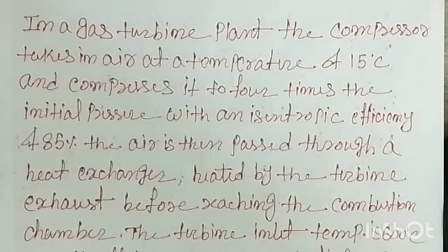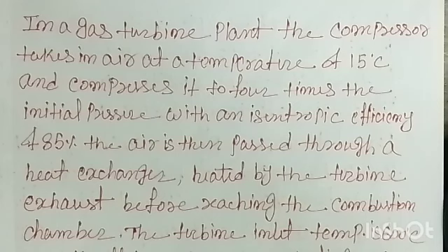Regeneration is the one in which we use the exhaust gases coming from the turbine. That exhaust gas is used to heat the air leaving the compressor before entering the combustion chamber, right? By doing so you can improve the performance of a gas turbine plant. Now, related to the regeneration method, we have one problem.